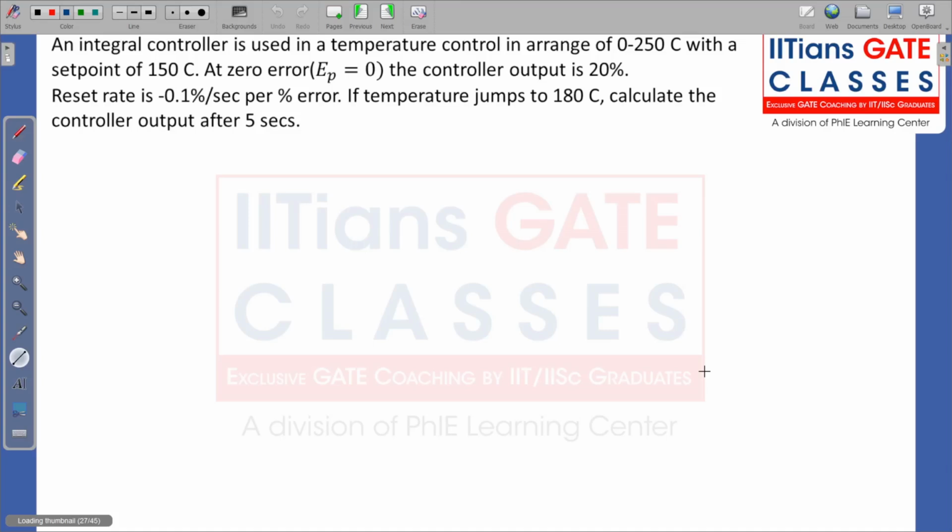So next we have a very simple question. I want you to pause the video and solve this question. An integral controller is used in a temperature control in a range of 0 to 250 degrees C with a set point of 150 degrees C. At zero error, EP equal to 0, the controller output is 20%. Reset rate is minus 0.1 per second per percent error. If temperature jumps to 180 degrees C, find the controller output after 5 seconds.